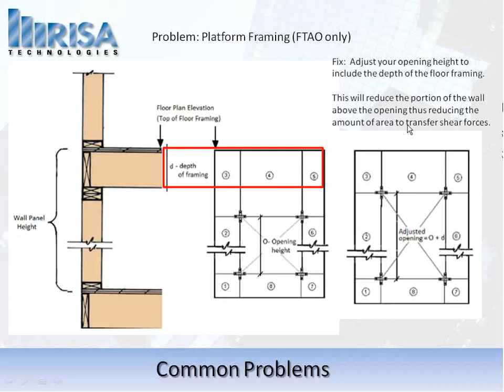Okay, so we can solve it sort of by opening up that area of the opening. And this might be something you might want to consider for force transfer around openings. This is really probably the only time that it really matters, for force transfer around openings. Because if you think about segmented, we actually take these sections and say they're ineffective. And for perforated, we don't really use those as well. Okay, so you really don't care too much about this big chunk unless you're in force transfer around openings.